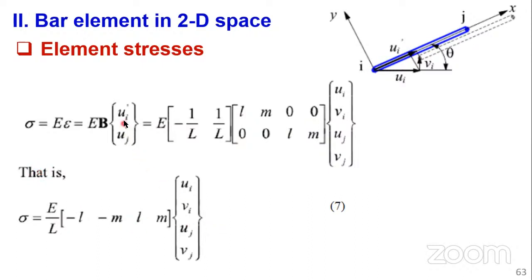Okay, what has happened here? We have just taken the U's, because in terms of stress for the element, remember we are talking of the element, not the global element, there is no stress that will occur in the local y coordinate. That's why you see we are just concerned with U_i and U_j, the axial components. So don't ask yourself why our matrix has condensed.